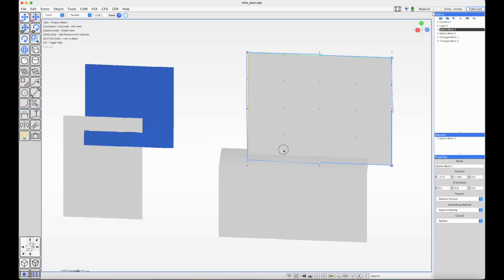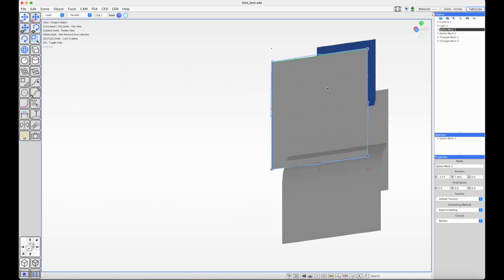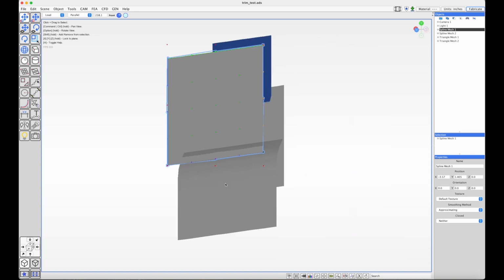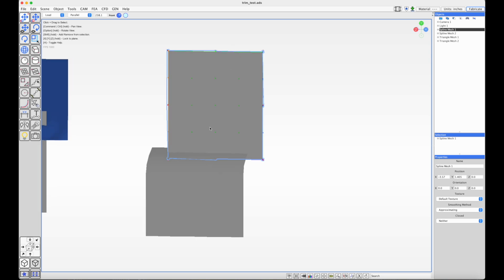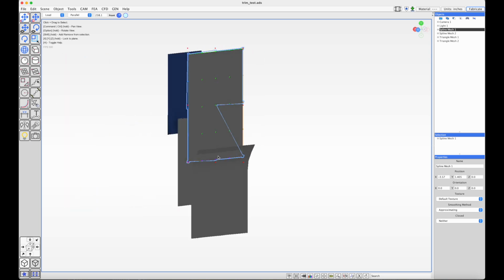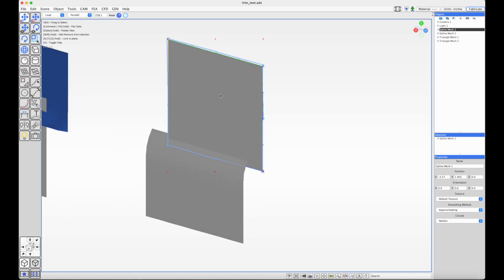To manufacture that though, because we want a mold negative, we want to actually generate the G code that will process make molds based on the backside surface. So the trim tool comes in where we can use the shape that we've generated, but we want to cut off this excess lip so that the G code can be generated based on the back surface. When we get our mold, then we lay it in the fabric. We'll get a part that represents this top surface.